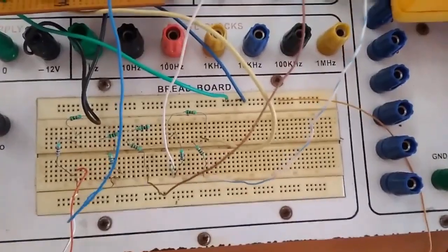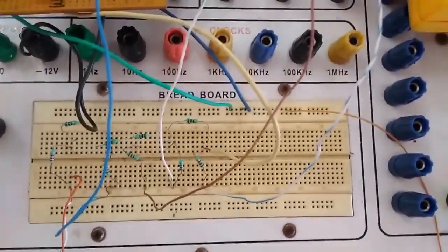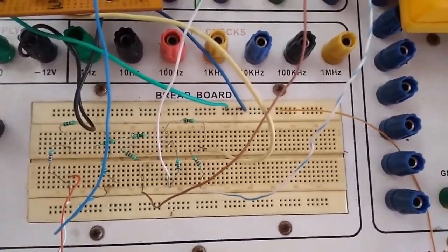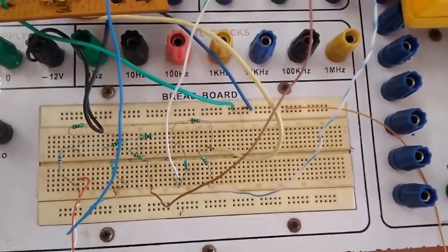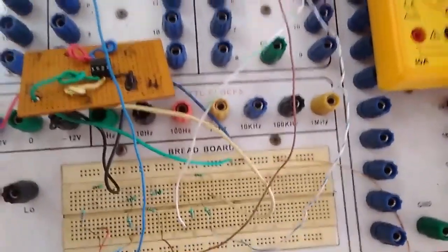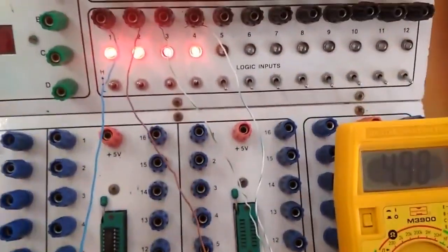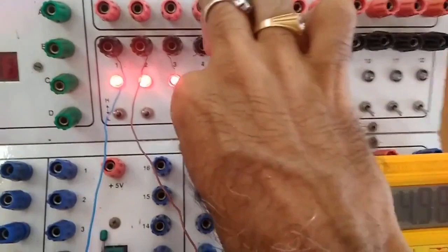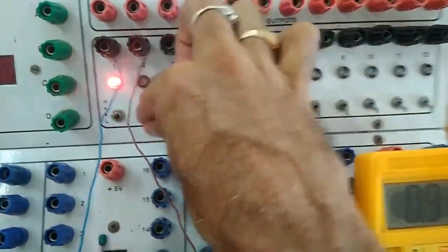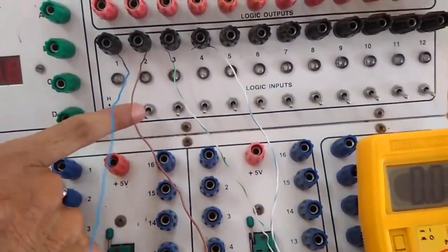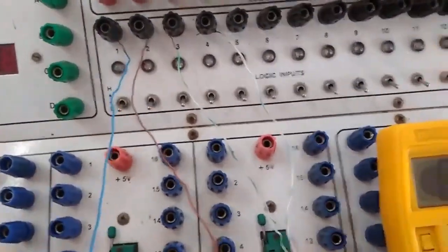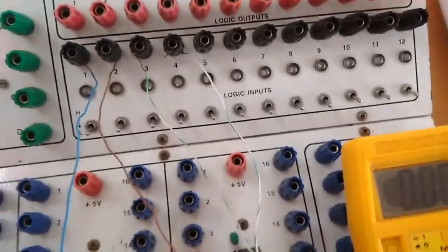Now going to the circuit diagram, this circuit is rigged up as given in the diagram in the manual. We have used R and 2R, that is 1K and 2K resistors, in the circuit. The inputs are given by using the switches on the digital trainer. Now it is 1111. I start with the initial condition of 0000. Here this one is the LSB and this is the MSB. Then I start with 0001.